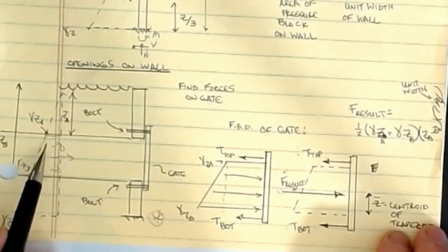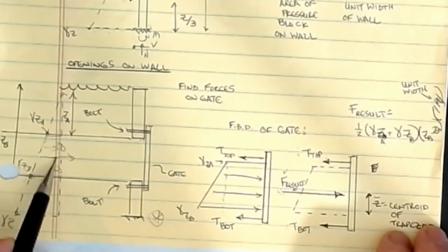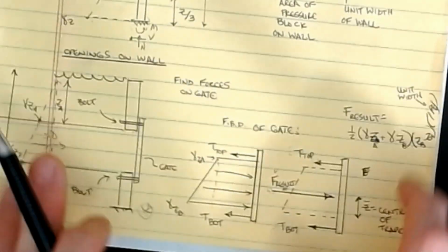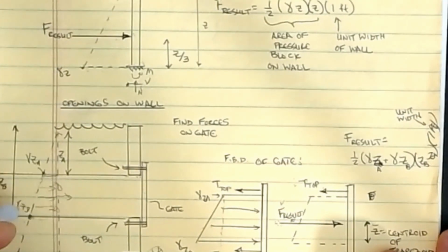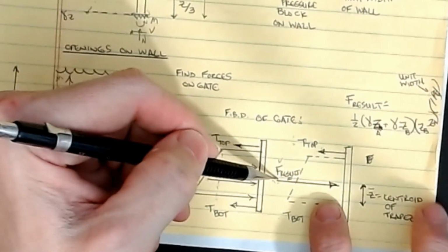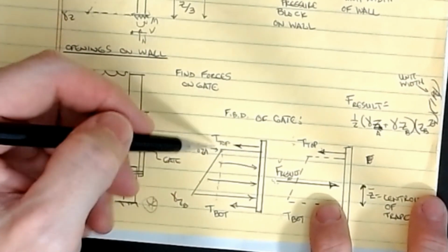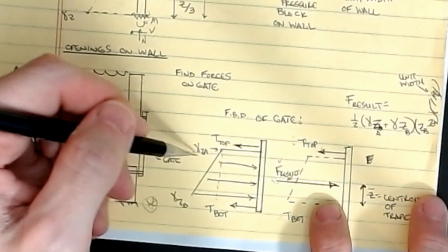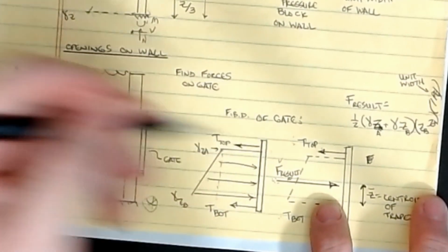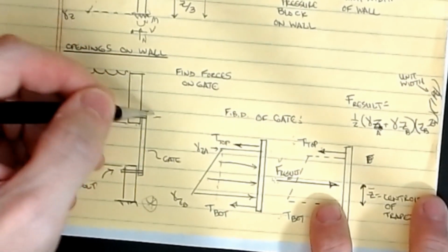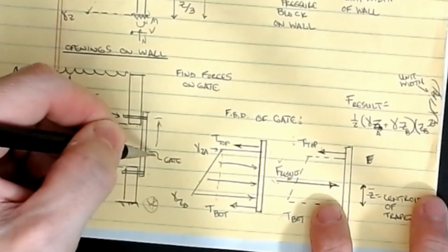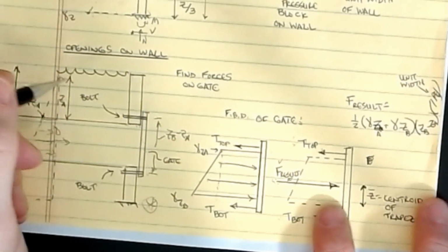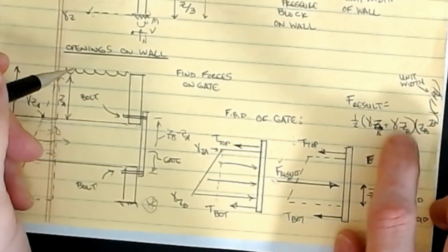Just imagine, here's the force of this trapezoid, and then it's going to slide over and hit whatever I want to be studying for those calculations. So it's pretty easy to do. We can get our resultant force itself. This resultant force is going to be the area of this trapezoid, which is 1/2 of gamma ZB plus gamma ZA, all multiplied by the height. If it's ZA to the top and ZB to the bottom, then this height right here is ZB minus ZA.